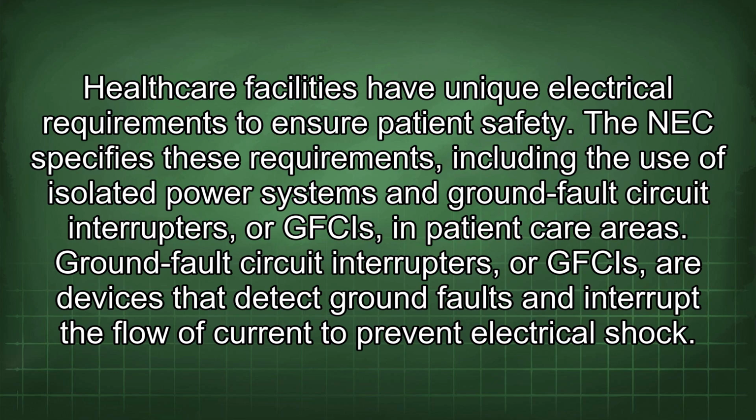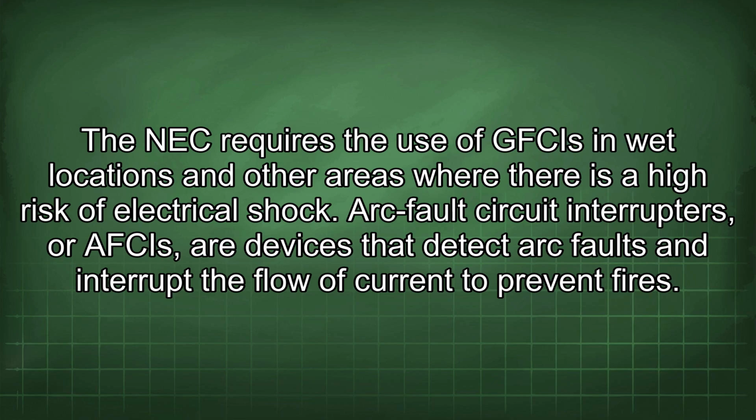Healthcare facilities have unique electrical requirements to ensure patient safety. The NEC specifies these requirements, including the use of isolated power systems and ground fault circuit interrupters, or GFCIs, in patient care areas. Ground fault circuit interrupters, or GFCIs, are devices that detect ground faults and interrupt the flow of current to prevent electrical shock. The NEC requires the use of GFCIs in wet locations and other areas where there is a high risk of